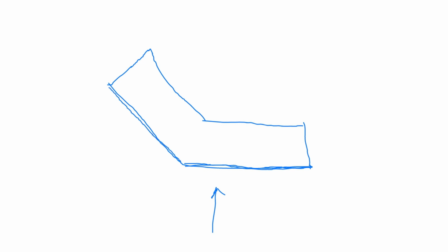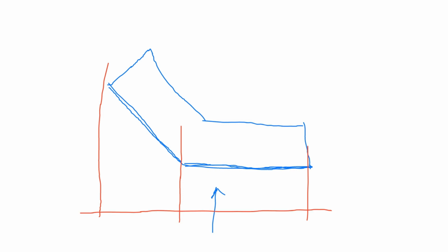We will not project any dimension, so if I make an elevation, I would come to here and drag lines similar to the architecture representations like this, drag a line from here and draw my ground line. This is the main elevation that I see, and this is going to be projected. In other words, every dimension that you see here will not reflect a real dimension. If you have windows, for instance, here, they will be projected so that it's not going to show exactly what the dimension of the window is, so we avoid having this.